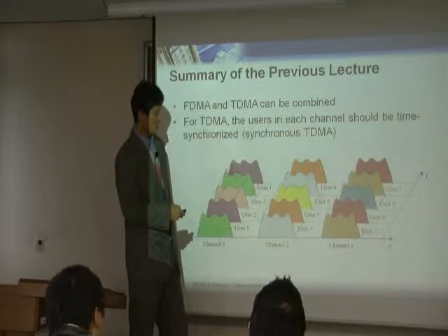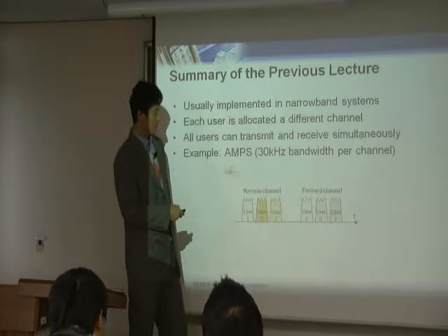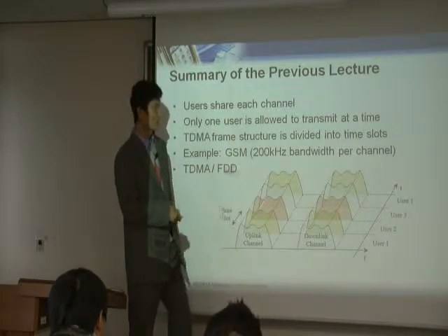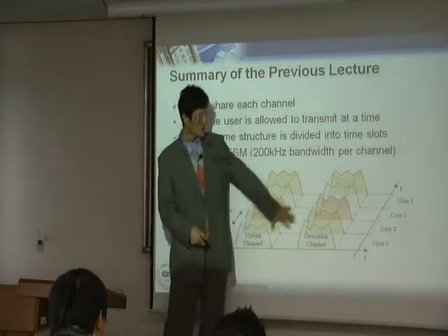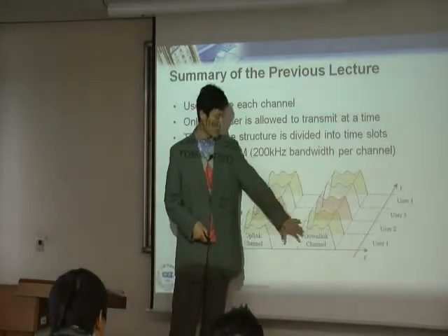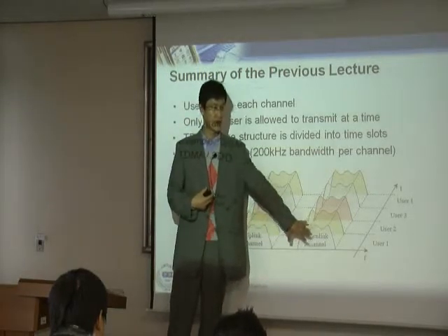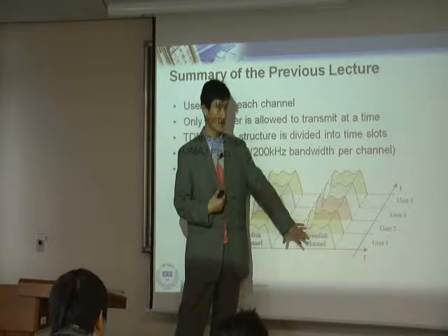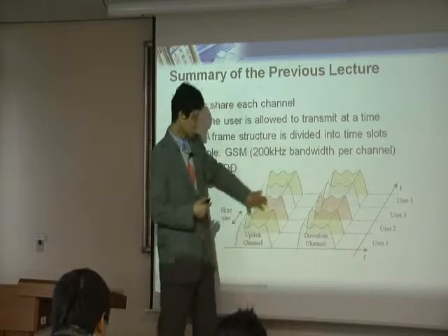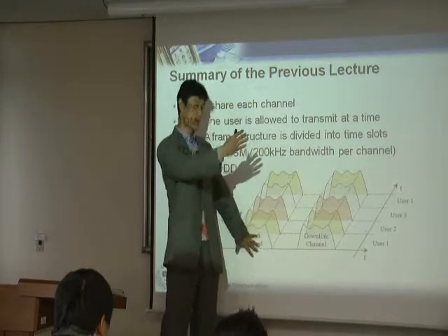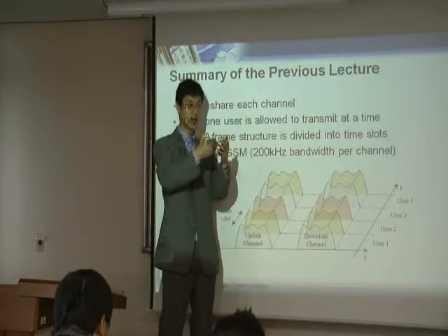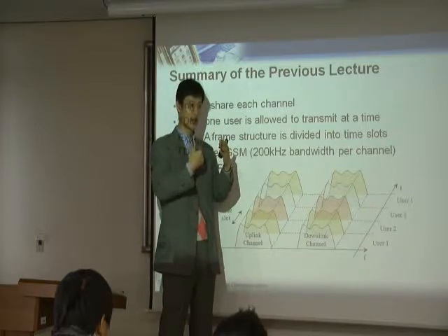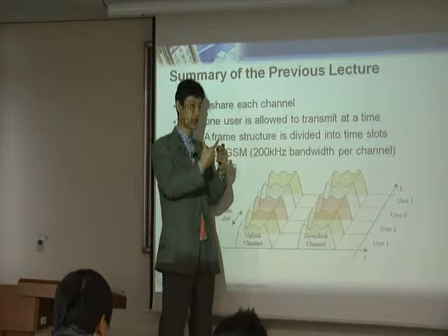Let's say I want to use this kind of system, uplink and downlink, an FDD system. When you think about an FDD system, from the user perspective, transmit and receive use two different frequencies. Therefore, you have to do the synchronization for each of them. Remember the picture that I showed you. For uplink, since you are transmitting to the base station, your transmission should be a little bit earlier than the base station time, right? Because that way, your packet goes through the propagation delay and is received